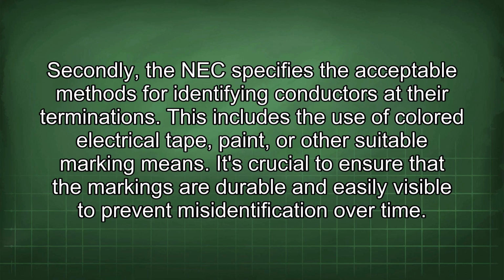Secondly, the NEC specifies the acceptable methods for identifying conductors at their terminations. This includes the use of colored electrical tape, paint, or other suitable marking means. It's crucial to ensure that markings are durable and easily visible to prevent misidentification over time.